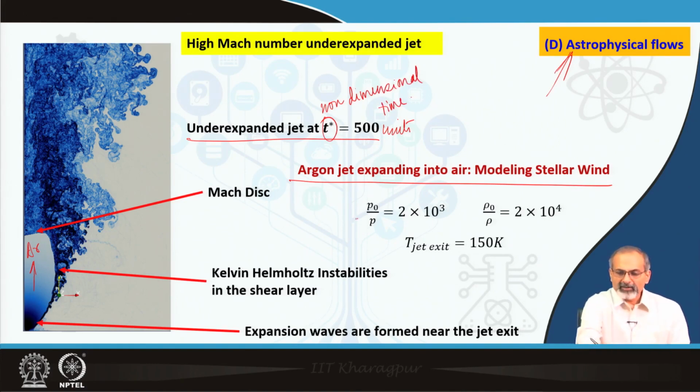And then if you look at the pressure ratios, density ratios of the pressure and density at the inlet in connection with the corresponding stagnation values, you see very large ratios. That means that the stagnation pressure ratios as well as density ratios are extremely high.